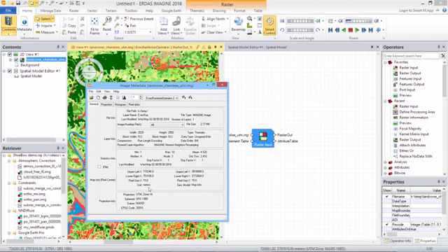But the main thing that we want to look at is in the map info section, that the pixel size is 15 meter pixels. So when processing raster data in the spatial modeler and doing a buffer or search operation to search away from a particular class to a distance of say 150 meters, because that's a raster operation, it operates in units of pixels. So if we've got 15 meter pixels and we want to search 150 meters, we're going to have to buffer around the water class by 10 pixels. 10 times 15 is 150 meters.